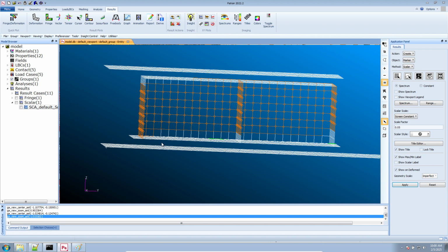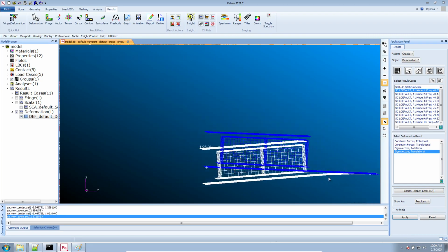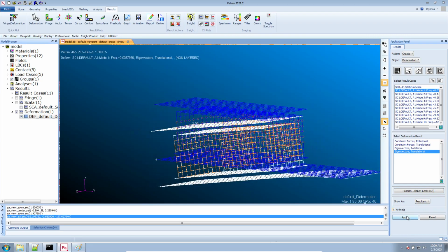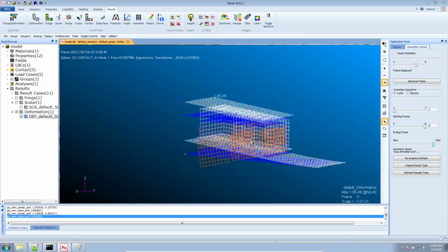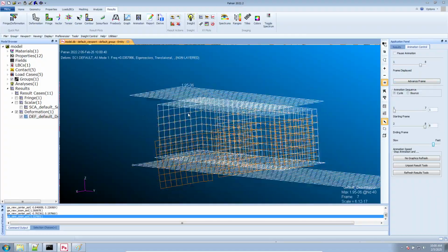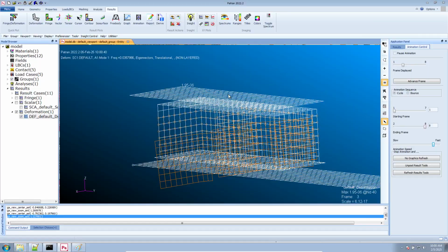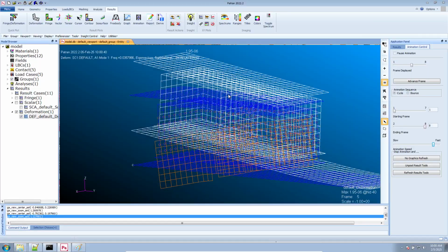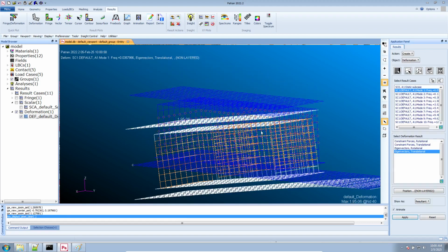not only what the mode shapes look like, so let's go and look at the mode shapes, we were able to look at the contact status. So here's what this mode shape looks like. Sometimes I like to animate it. Let's go ahead and slow this down a little. So you can see that the meshes have a mode shape that's consistent. They're not technically moving together, but if you wanted to think of a mode shape as movement, then yeah, they're moving together.